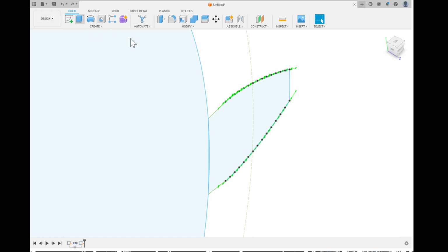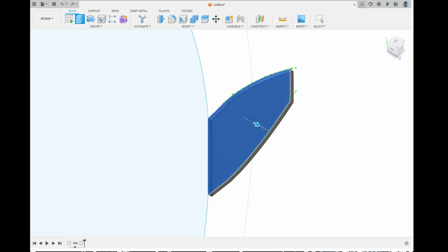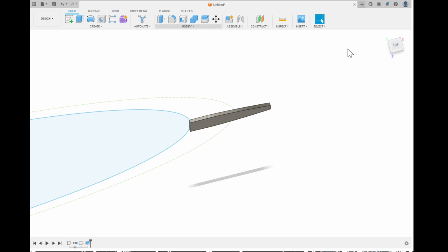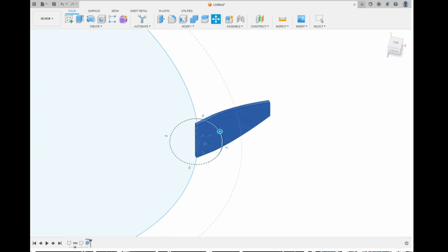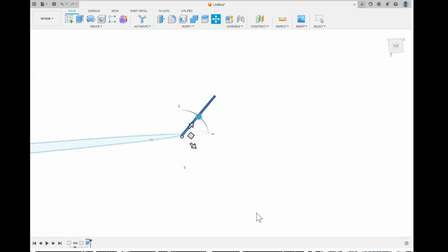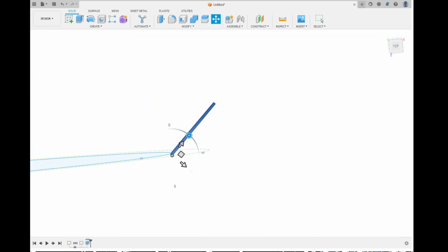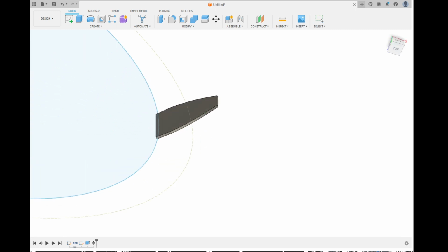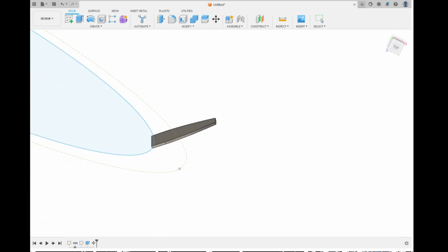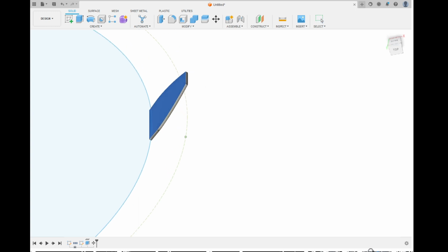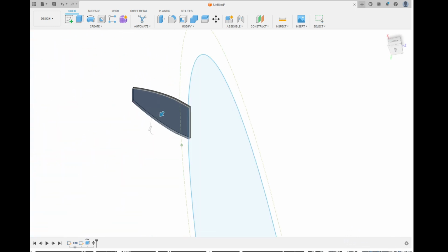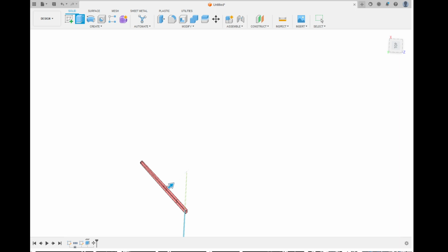All right, instead of copying that, instead of rotating that sketch, we're just going to make it into an object. Make it into a 1mm object, and then we'll just rotate this object. That might be the easier way to do it. Move or copy. We'll select this body, and we will rotate this body at 45 degrees, like so. And then we will select this body out at 45. We will extrude it now to the length that we want it to be.